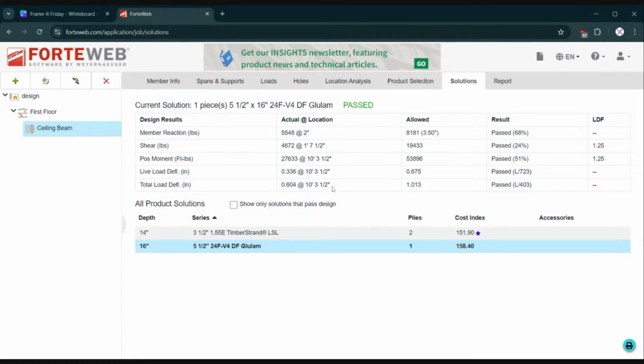Now over 20 feet, a glulam is normally cambered by about 1/4 inch in 24 feet. So when we set dead load on top of this and build the structure, it's going to level itself out. And then over time with total load, it's going to deflect 1/4 of an inch. So we don't want to go less than 16 inches here, because we would bend too much. We're not going to break, because that's just not the limiting factor. And we increased the width of our contact patch, so we've got plenty of capacity for weight.